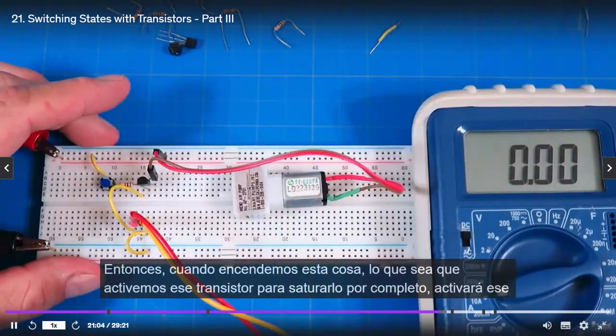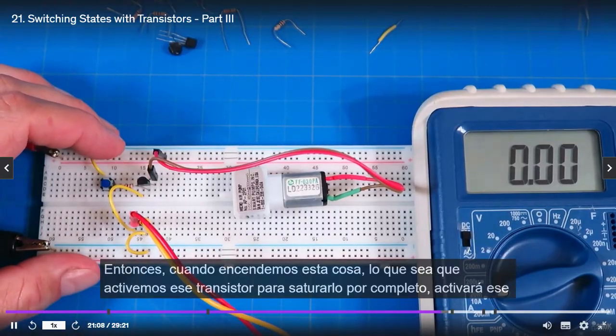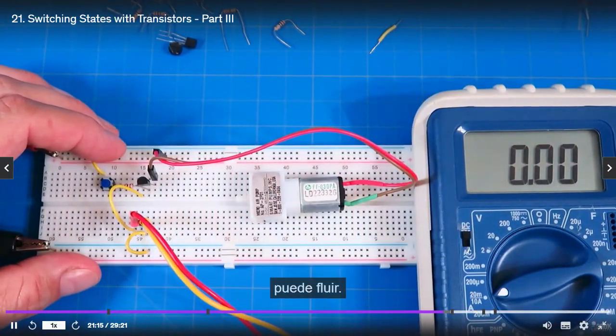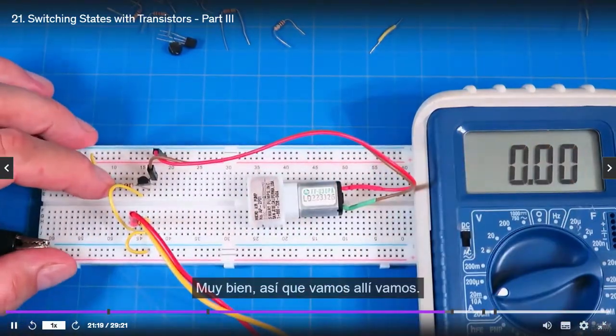So now when we turn this thing on, whatever we turn that transistor on to, fully saturate, it's going to turn on, let current flow, and the load will be the motor, and the motor will dictate the maximum amount of current that can flow. So let's see what happens, and the transistor is just going to act as a switch. All right, so here we go.